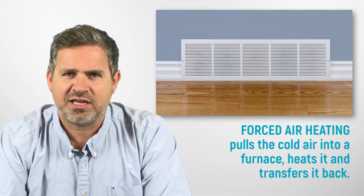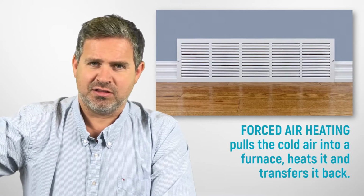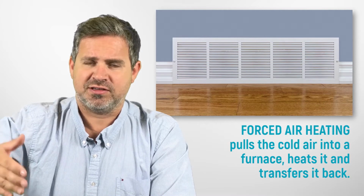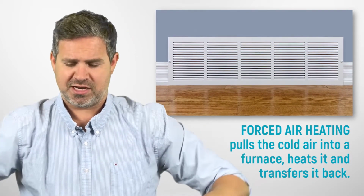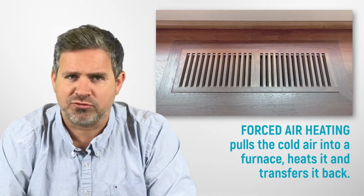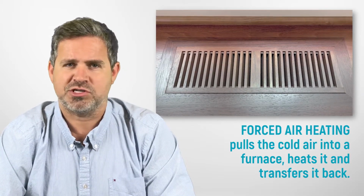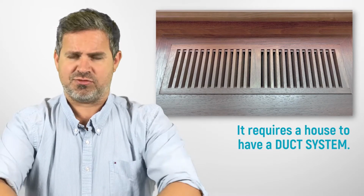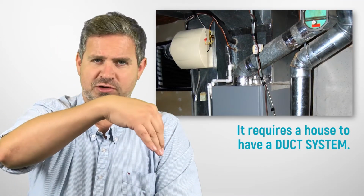So forced air heating, essentially what it does, it pulls in the cooler air throughout your house. If you have an existing forced air system, it pulls the air in through the cold air returns. Those are those long rectangular grills that you'll see in the hallway. There's usually one per floor. Sometimes in older homes there's a lot more cold air returns, but let's say there's 3 or 4 of them. It sucks in air from these cold air returns and brings it back to the furnace area.